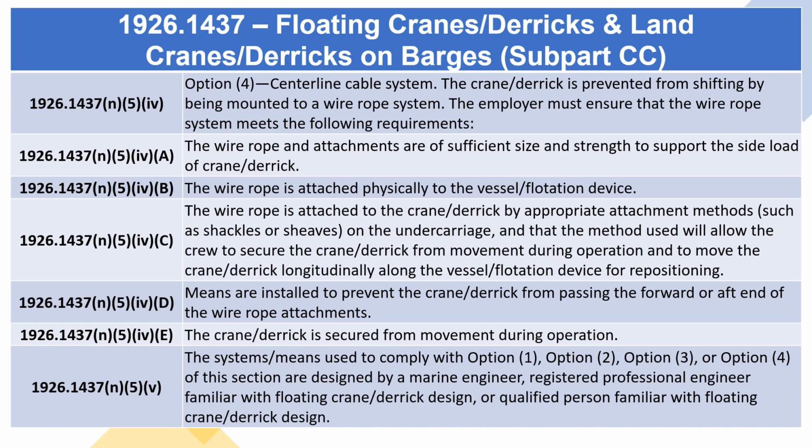1926.1437 N5 4. Option 4. Centerline cable system. The crane/derrick is prevented from shifting by being mounted to a wire rope system. The employer must ensure that the wire rope system meets the following requirements. 1926.1437 N5 4 A through E.